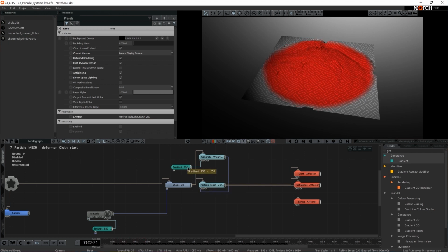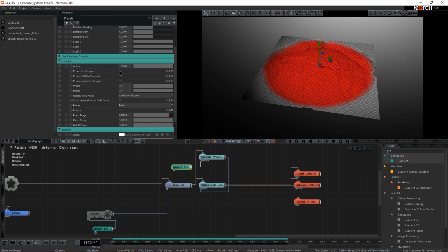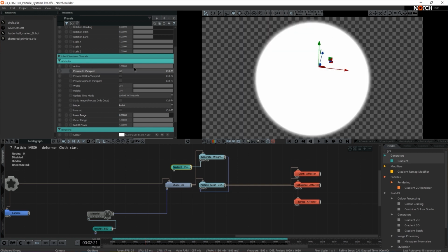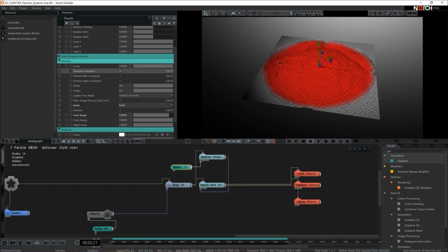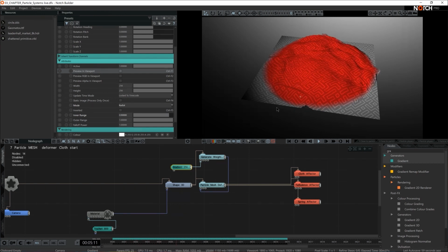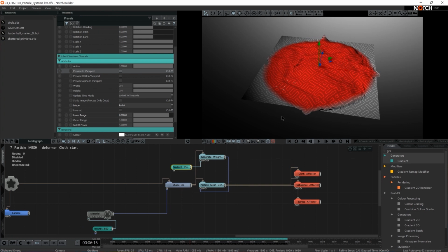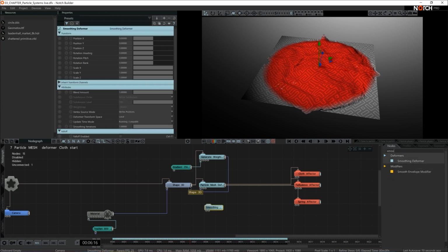And there we go. As we've spoken, we have two areas of influence. The center is where the simulation is taking place, and the corners is where it's pinned down. It's doing what I requested. It's definitely working, but it's not looking smooth. It's not looking slick. So if we think back to the deformers chapter, you might remember that we used something to address that. So we do have smoothing deformer. So I'm going to add that as a last point in the chain.